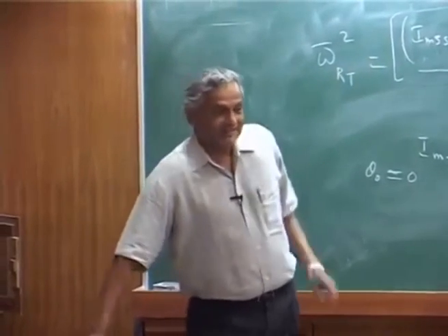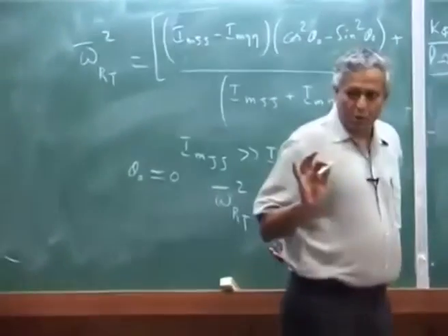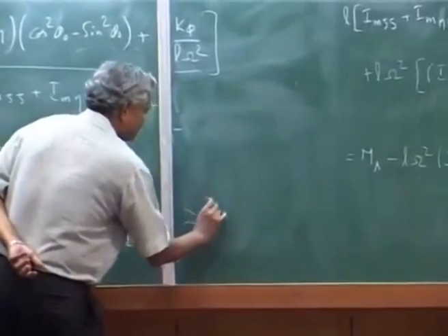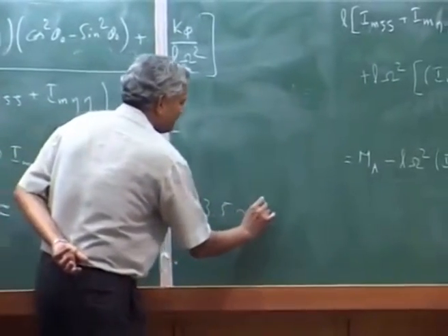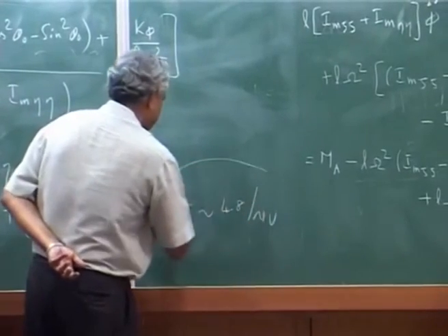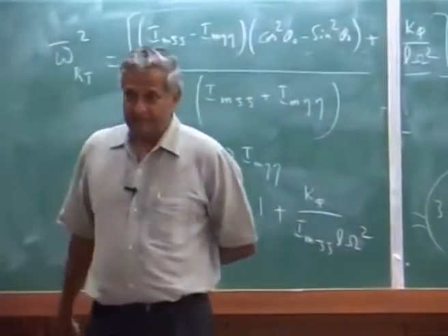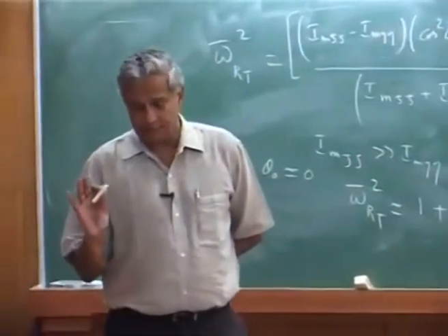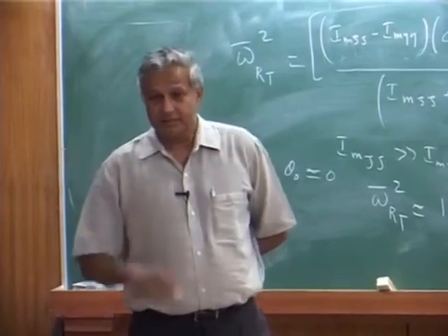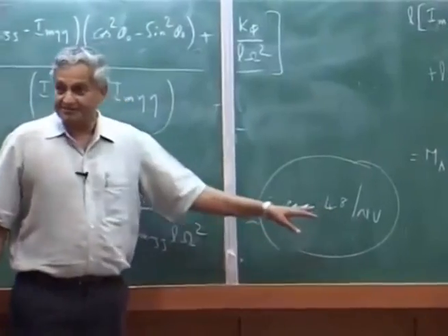Far away means usually it is around 3.5 to 4.8, something like that, in this range. 3.5 is low torsional stiffness, very low, a torsionally soft blade. But you see this frequency is far away from flap and lag.